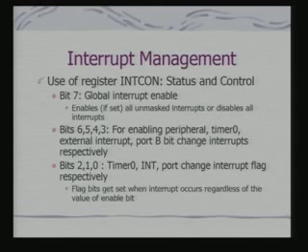I have listed the significance of the bits in the INTCON register. Bit 7 is the most significant bit because it is the global interrupt enable/disable bit. And if we disable this bit, the PIC will not respond to any pending interrupt.